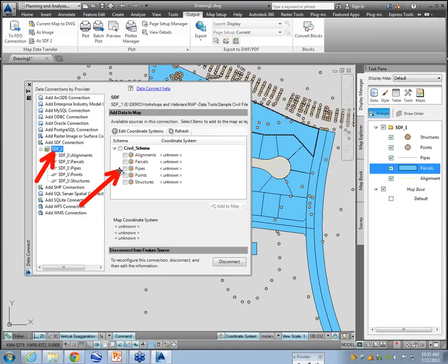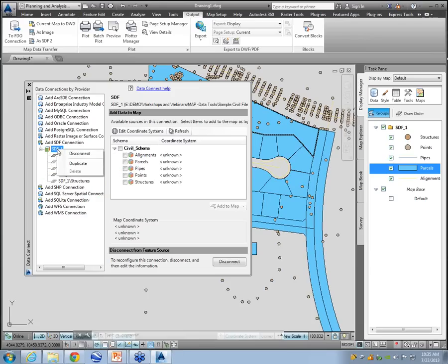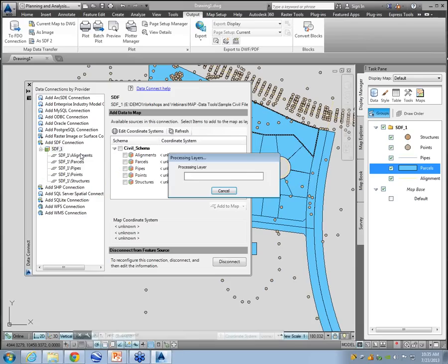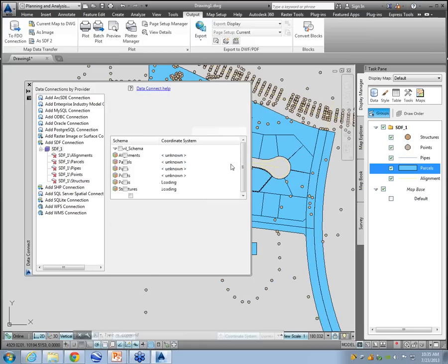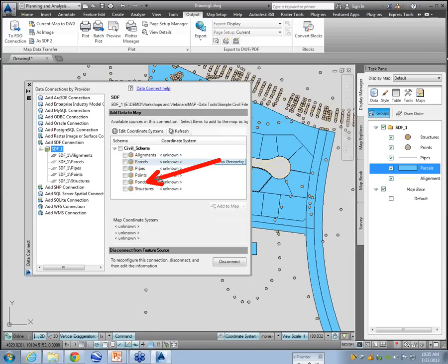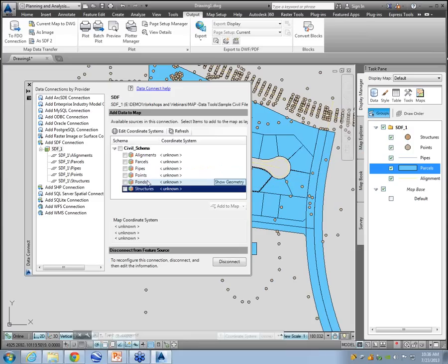Looking at this, okay, Warren, you lied to me. Where are your ponds? All right, I've got to disconnect my existing file and then reconnect it. Then it finds everything new that you put in there. Don't ask me why. I just wish it would pop up on its own, but you have to disconnect and reconnect. You would think that hitting refresh over here would get all of that, but you don't. All right, so there's my ponds.